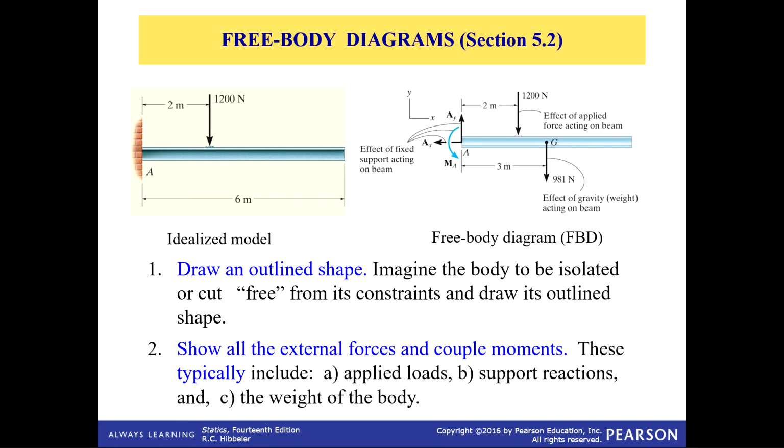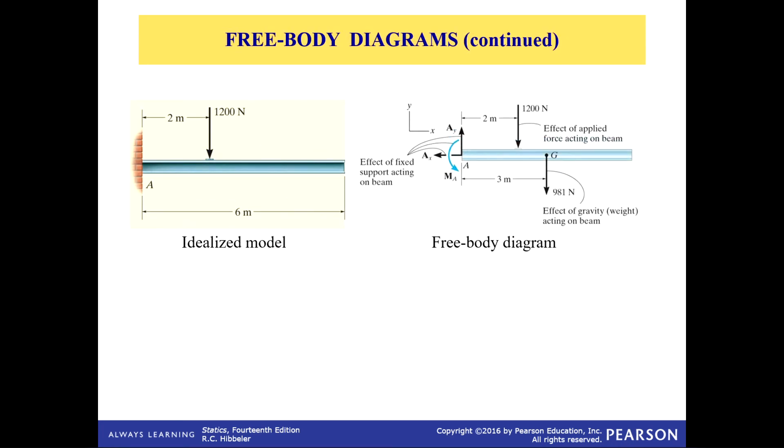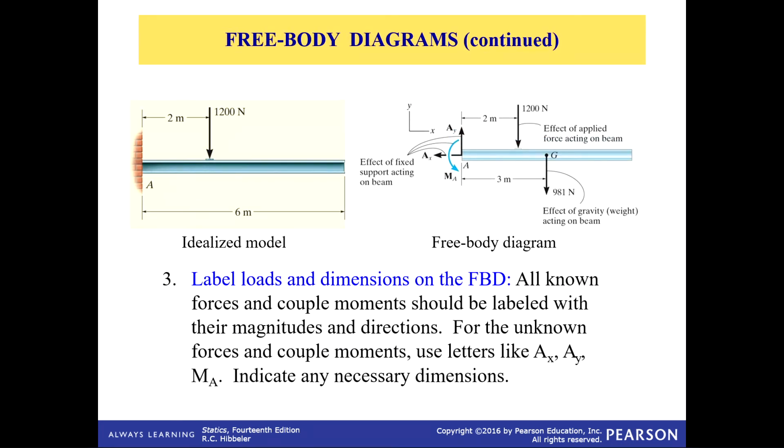the outside world, add your external forces, your reaction forces, and let's see what the last step they tell us here is. Label the loads and dimensions on the free body diagram. Right, once you get to that point and you've got your free body diagram, you apply your equations of equilibrium and you can solve for your unknowns. Simple as that.